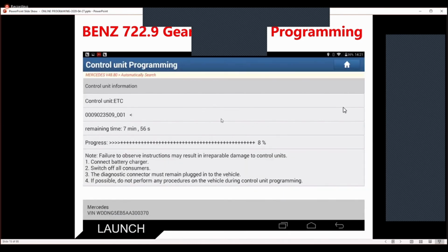press OK. And then what we're doing is we're flashing the ECU. So we wait until it gets to 100%. Do not interrupt this. The bottom area is most important. We call it a battery charger, but you would use the FPF 100, the maintainer. Make sure that these conditions are met, and wait until the arrow is at 100%. Once that's completed, then it's flashed. It can't be interrupted.